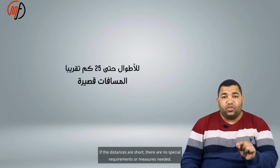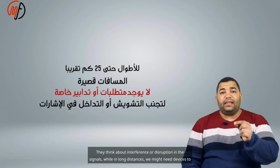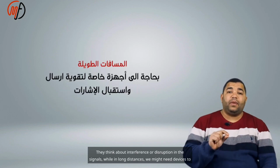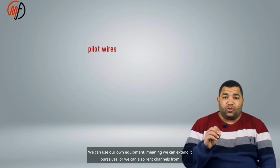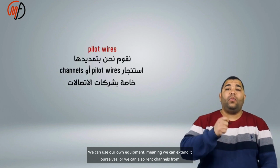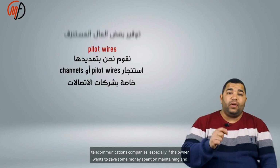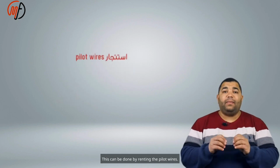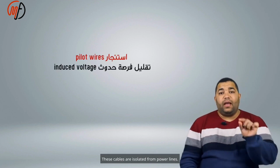If the distances are short, there are no special requirements or measures needed to think about interference or disruption in the signals, while in long distances, we might need devices to amplify, send, and receive these signals. We can use our own equipment, meaning we can extend it ourselves, or we can also rent channels from telecommunications companies, especially if the owner wants to save some money spent on maintaining and installing these cables. This can be done by renting the pilot wires. These cables are isolated from power lines.